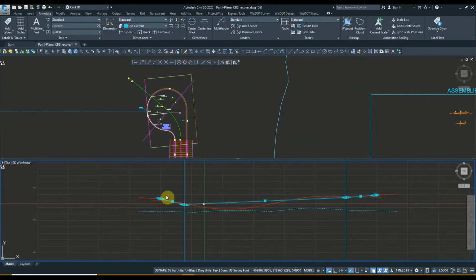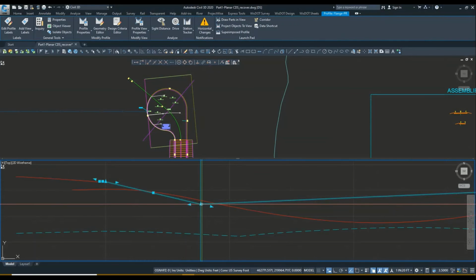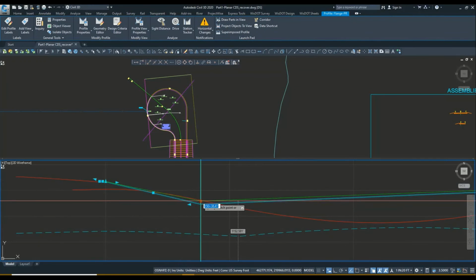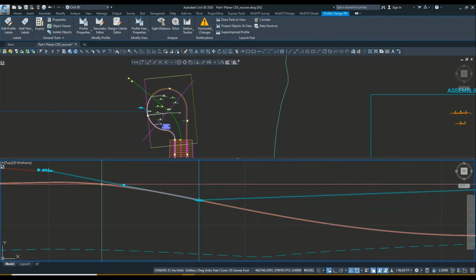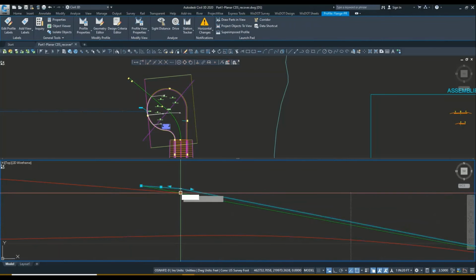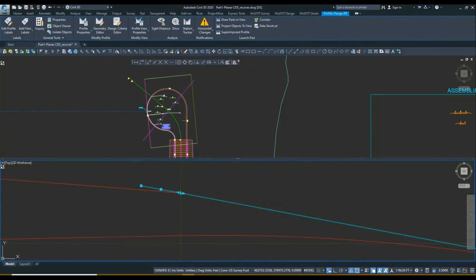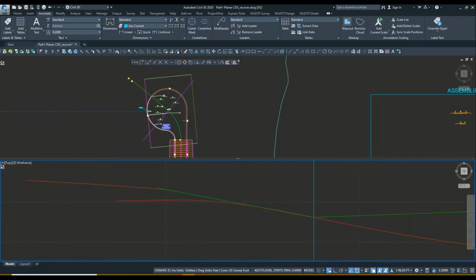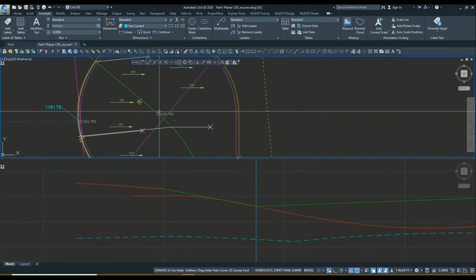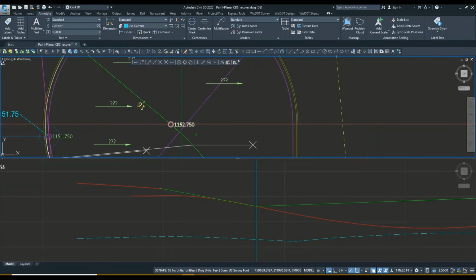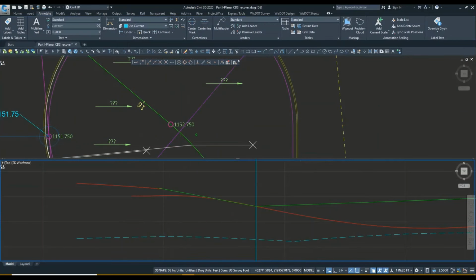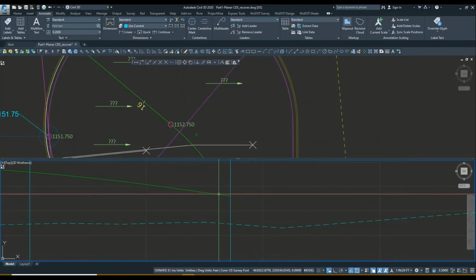All we have to do is adjust right here, which is where the setup surface starts. And we'll go ahead and adjust this location. I guess before I do this part, I'll make sure that this spot elevation was also updated, so I'll make sure that this changes as well.